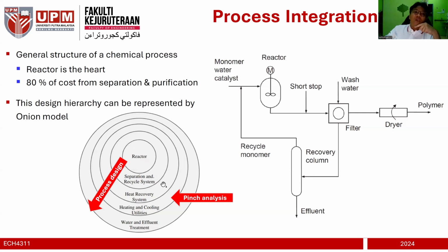And then after you have completed all of that, you can recover heat, because heat recovery matters. Let's say you don't do any recovery. All of your operating cost comes from the utilization of steam produced from the boiler, right? So let's say the process uses 1 ton per hour of medium pressure steam.